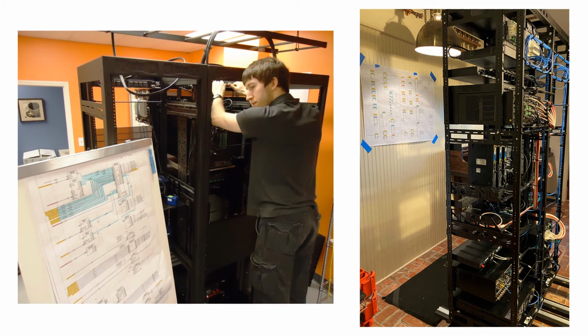Shown on the left, the printed schematic page is often used as a wire schedule for racks and room electronics. Each line on the diagram is highlighted only after each cable is routed, terminated, and labeled, allowing any installer to come in the next day and pick up where they left off. And different text can use different colored highlighters. In the right image, you can see the head-end schematic page taped to the wall to help in tying in a newly delivered head-end rack to the existing house wires.